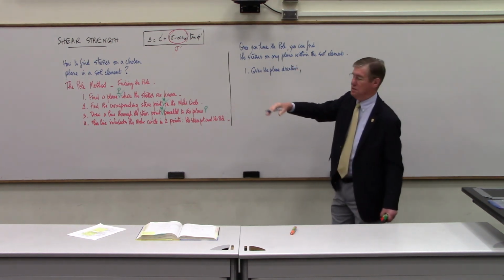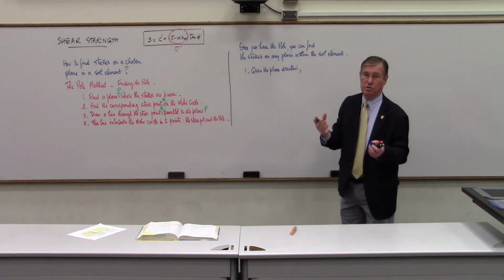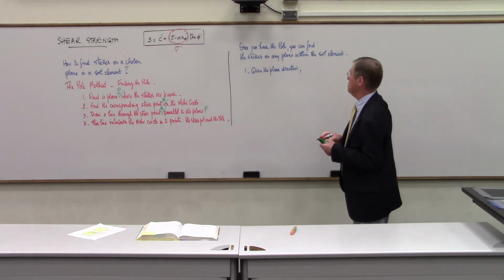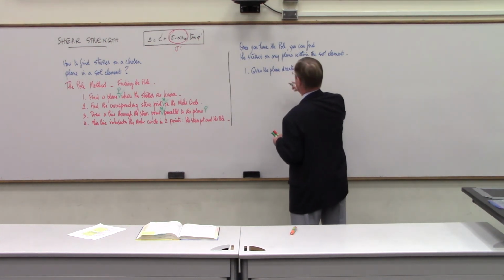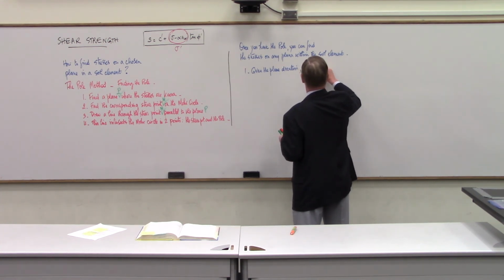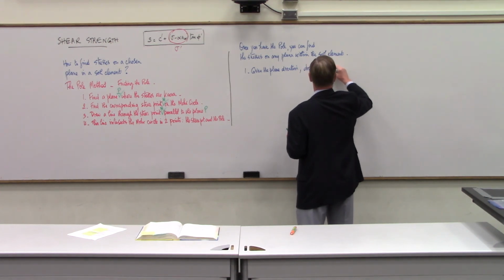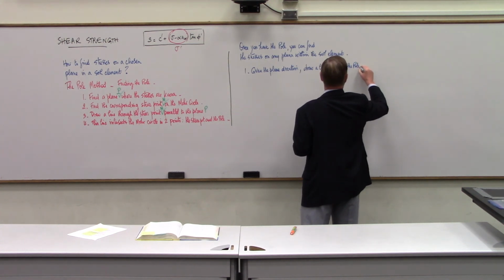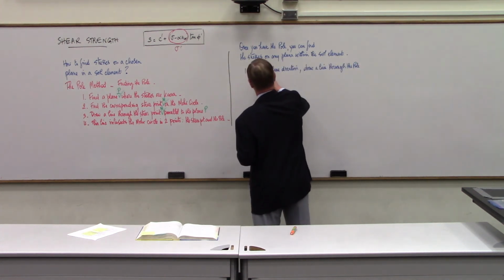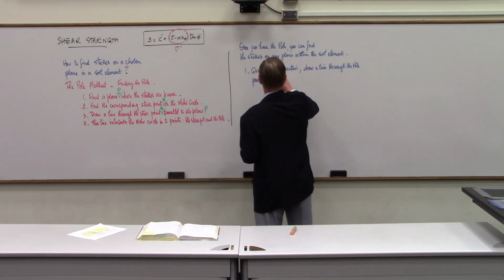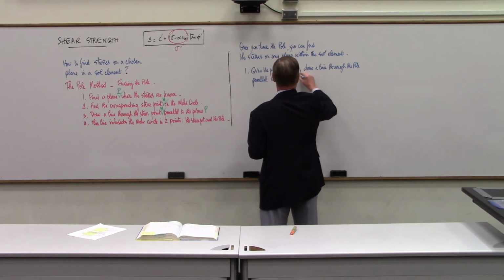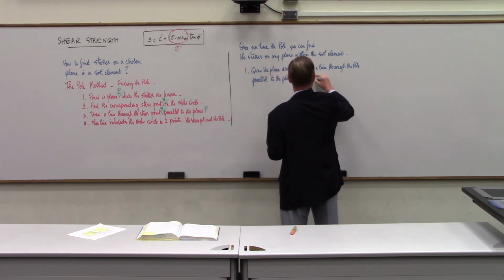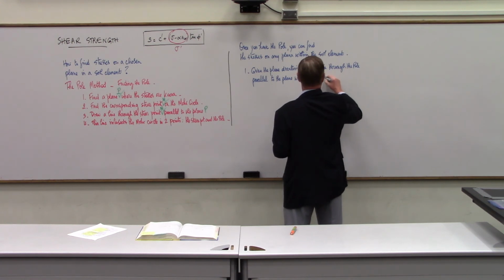and I know this is a lot of do this, do this, do that. You will understand a lot better when we start doing those practice problems. Given the plane direction, draw a line through the pole parallel to the plane where the stresses need to be found.